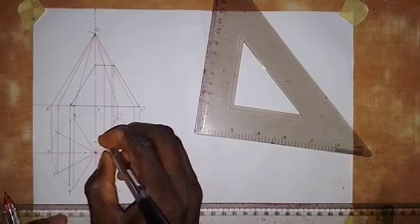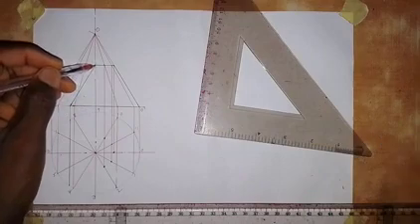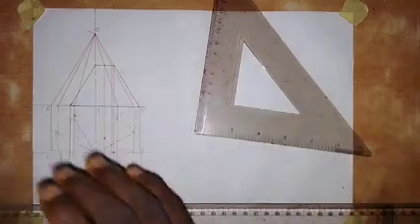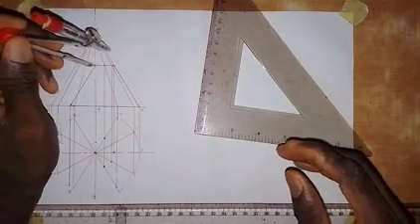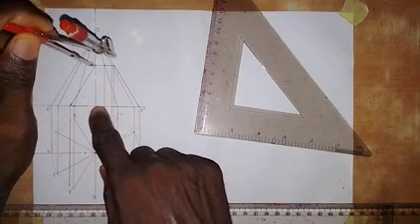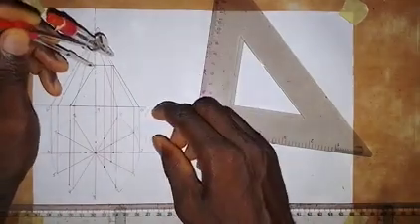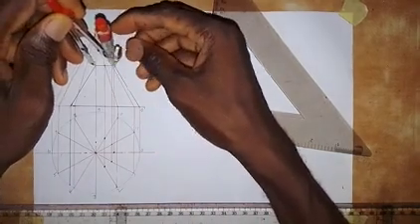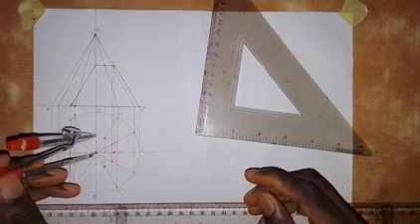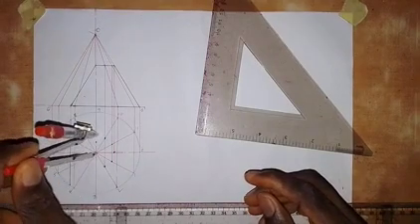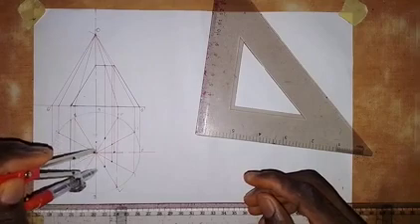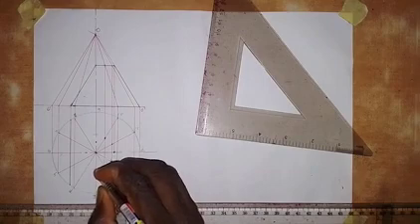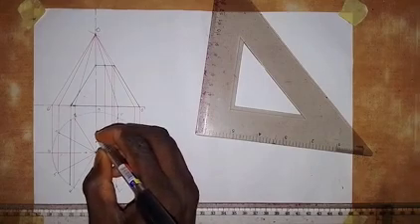Now, how do we locate 3 and 9? Because this line is not a slant line, it's a vertical line, what we need to do is take a compass and take the distance from this line. This line contains 3 and 9. So we put the compass at this point on the line, then extend it to this point on this slant side. Then we put it at the center here for 3 and 9 and make an arc here. This point is for 3, while this point is for 9.